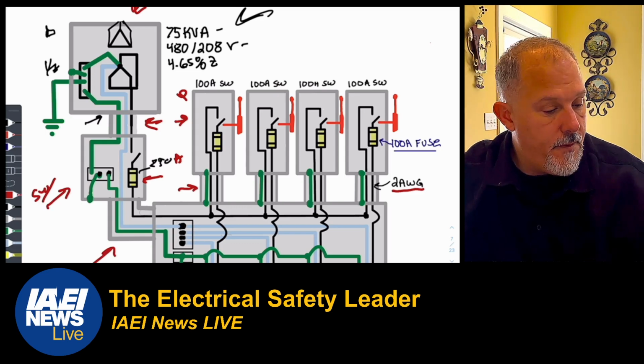Remember, those conductors are not protected at their ampacity. So you've got to be mindful that the conductor has to be protected, just like service conductors. We protect service conductors, right? We go to the nth degree to ensure the protection of those service conductors. Why? Because it's very similar to this. They come out of that system, they're not protected at the source, so we have to put protection around it. And we're doing the same thing here.